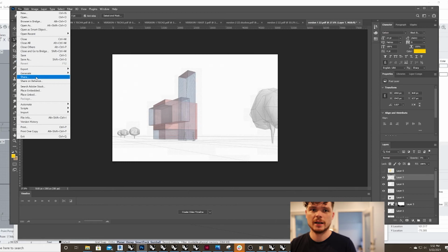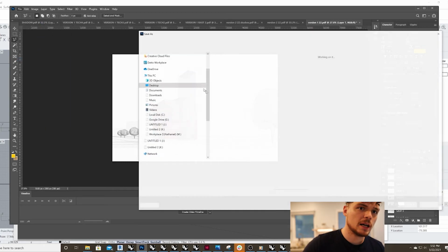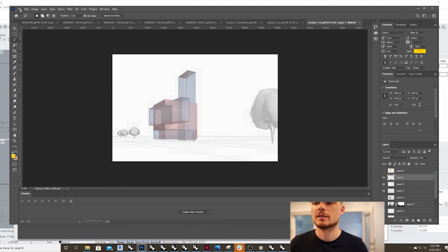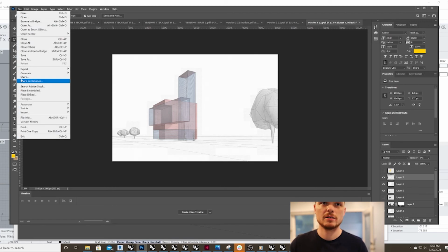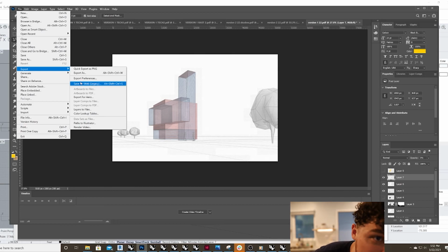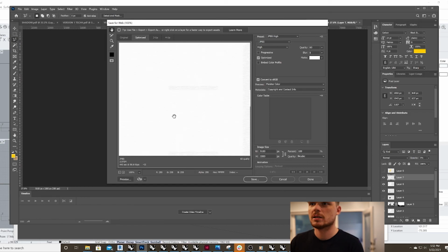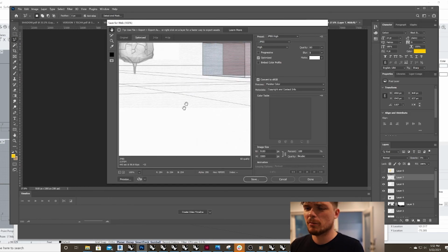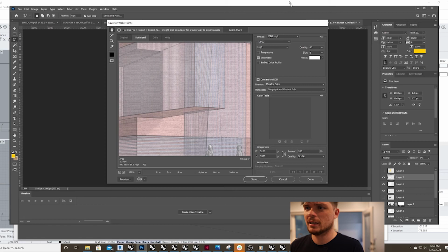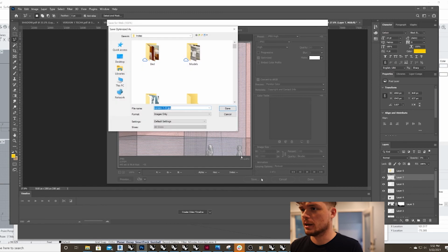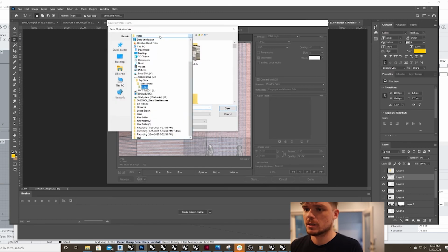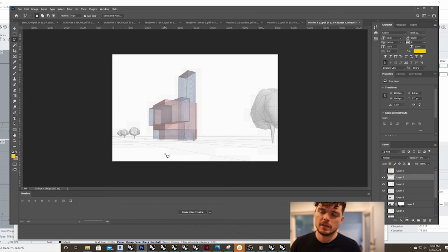And then you just go File, and I really like to go Save As. No, I don't like to do Save As. You can go File. Well, obviously save the file, but to export it, you can do Save for Web, and that just produces a high quality image, but one that's not just overbearingly too big, sorry. All right, and then we just save this out. All right, so that's just to give you an idea of really customizing the materials within Rhino so that you can do less work afterwards.